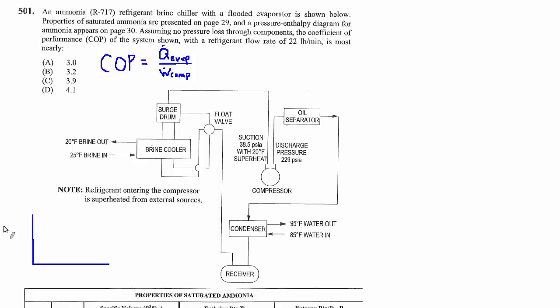But just to be really general for a minute and almost as a reminder about what a refrigeration cycle looks like on a P-h diagram, we have some saturation curve for a given refrigerant, and before the compressor we usually have a saturated vapor or a slightly superheated vapor, and then there's this isentropic compression. So we'll call that initial state, state 1. Then it goes through the compressor, isentropic compression. Now we have a high pressure saturated vapor. We call that state 2.